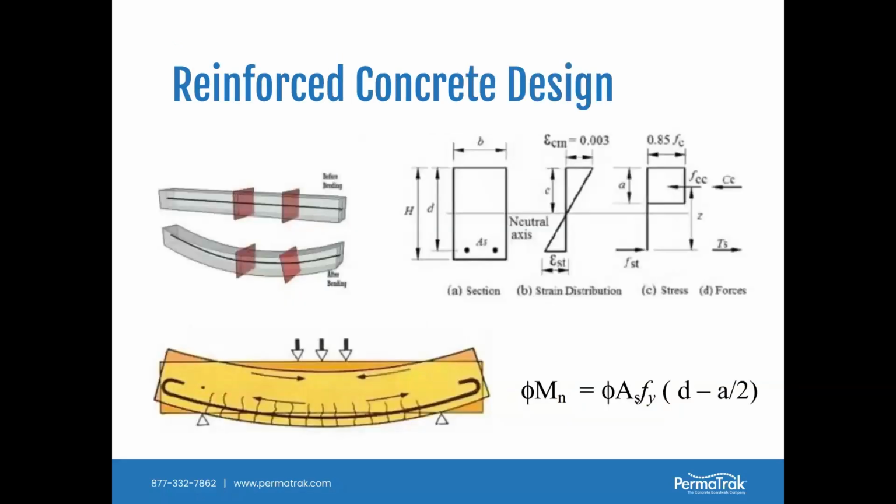Now, once you have decided what your loads are, you have to start designing the materials themselves. Going back to some of my structural engineering classes, from a reinforced concrete design, since that's one of the materials we're looking at, reinforced concrete is designed as a rigid beam member as a load sits on top of the beam. The top portion is in compression and the bottom is in tension. That's why the heavier reinforcement, steel, is added to the boardwalk to take those tensile loads. And typically there isn't much needed to handle the loads in the compression zone.